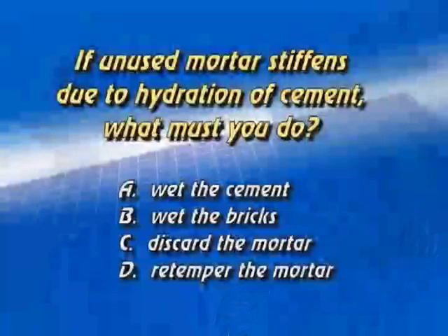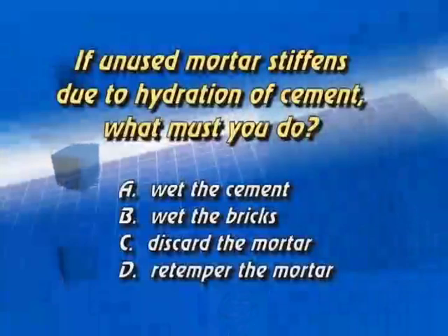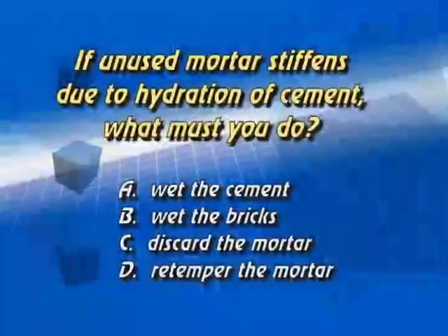Number 36. If unused mortar stiffens due to hydration of cement, what must you do? In other words, you're laying brick, the mortar that you're using begins to get stiff, it's beginning to set up. Can you add a little water? Can you retemper it, which is pretty much the same thing? What's the correct answer? No, you need to discard it and start anew with a fresh batch of mortar. So the answer would be discard the mortar, C.